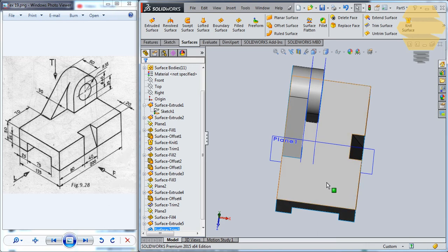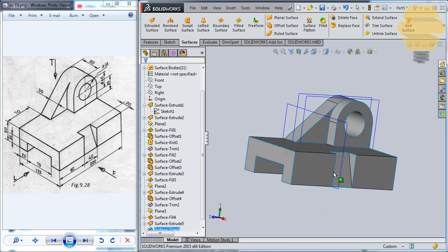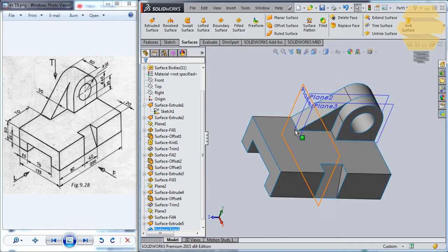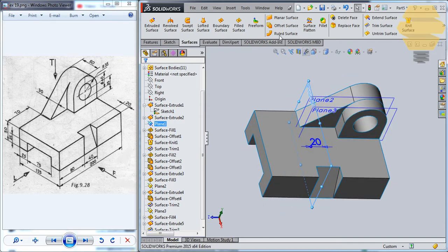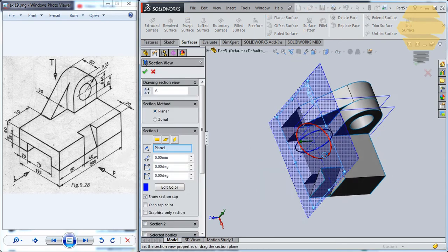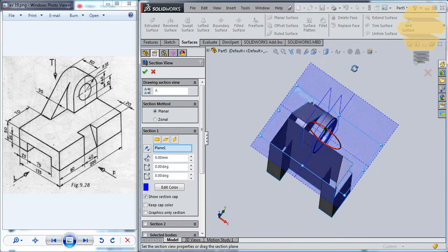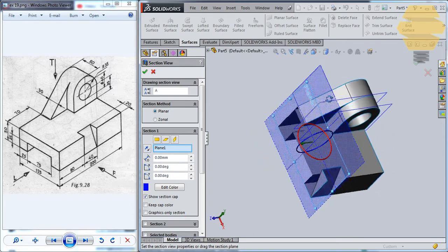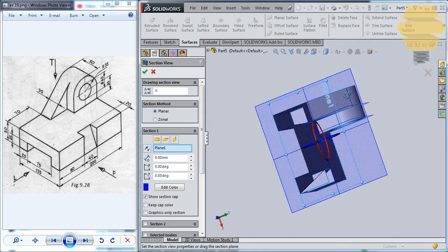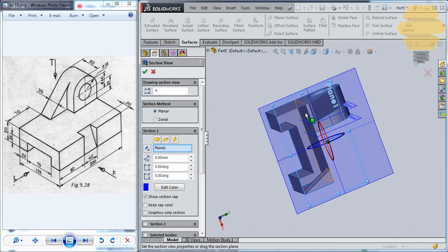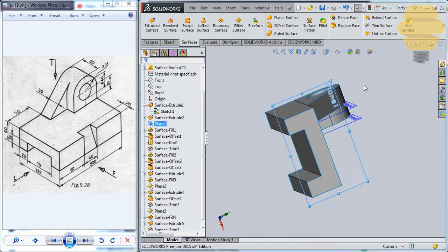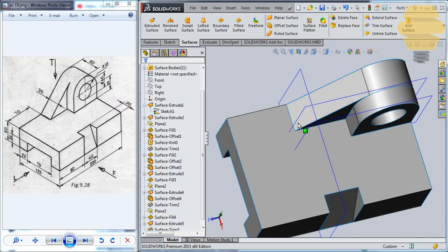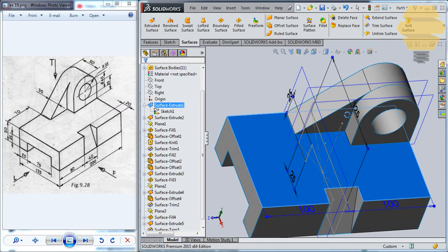So now we have a continuous surface model which can be converted to a solid. So now to check its continuity, you can select this plane here and go for section. You can see the section view of this. And what we can see is perhaps this model is not pretty continuous. As you can see here that there is a surface that still needs to be trimmed off. So you can still just go ahead over here. You can see that this surface still needs to be trimmed.